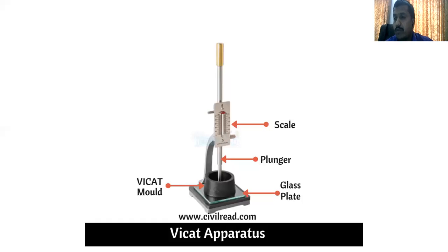Within 3 minutes actually. Why? Because after 3 minutes the heat of hydration process starts and the cement gains strength and starts hardening. The heat is liberated from your paste, and that is why the cement starts hardening.